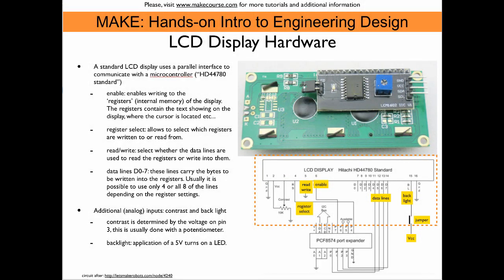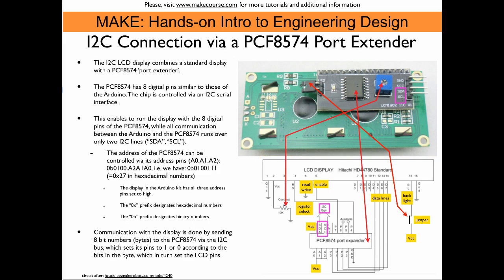So let's examine how the I2C module is connected to the display. This is shown here. The red arrows try to show what's hooked up where. First, the blue block is the potentiometer with which we can adjust the contrast. If your LCD display doesn't look happy, then just put a screwdriver in there and turn the potentiometer left and right until you experience good contrast.